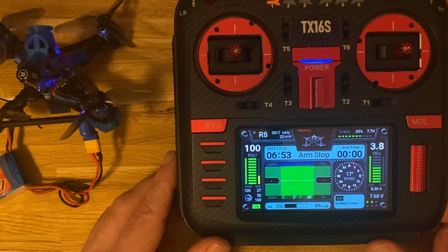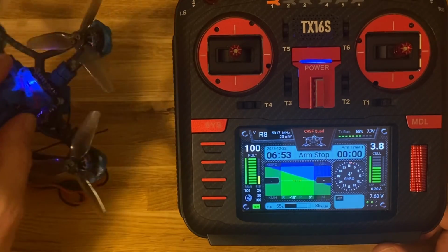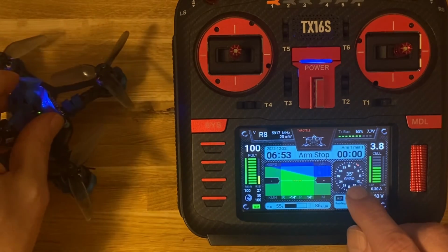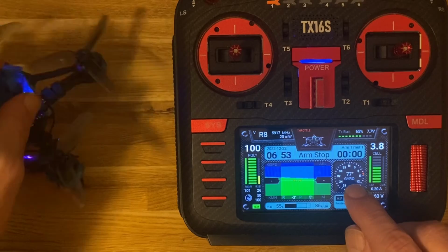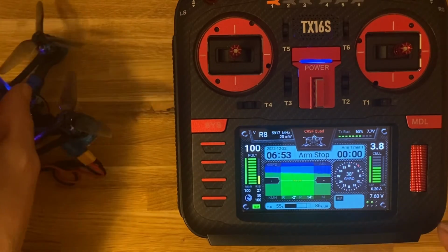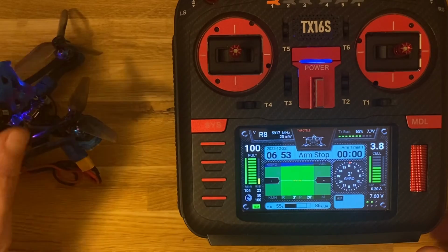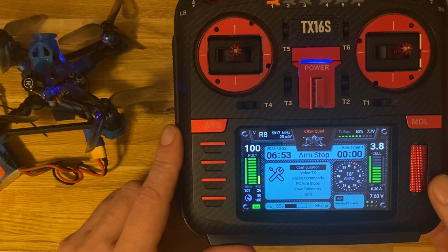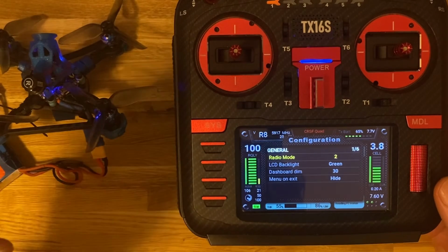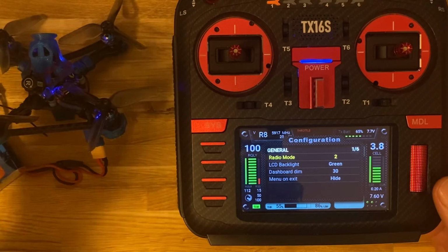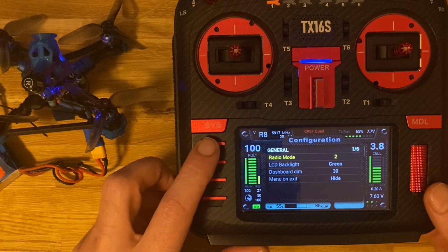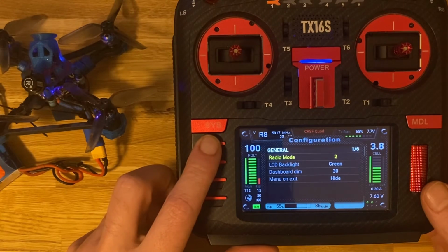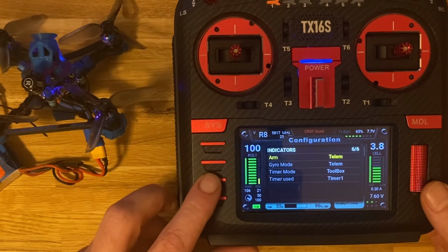Okay, what else is changed? Of course, pitch and roll is available, so you can see, and yaw is also available. No GPS, so it's just yaw position from gyro. And that's it. The change is in VTX. So if I go to configuration, I have VTX connected to receiver, not to flight controller. So Toolbox is checking directly CRSF protocol VTX status. And let's go to VTX settings.